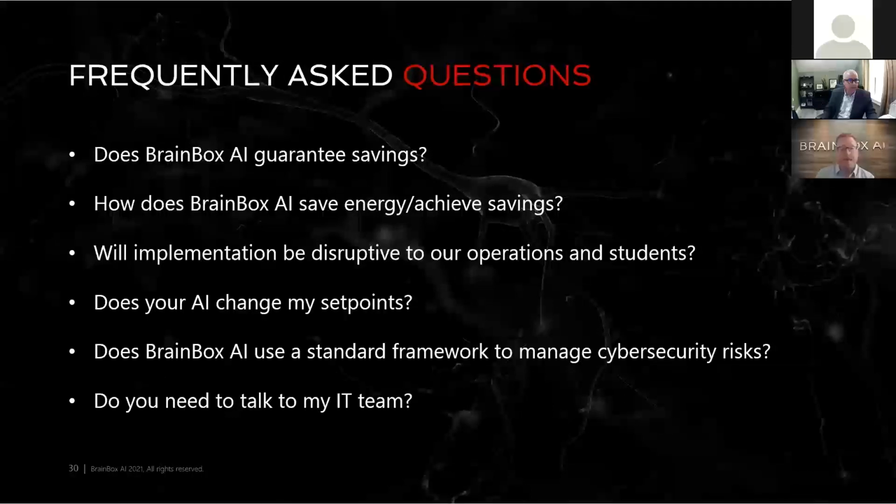So every 5 minutes it sends the data to the cloud and it asks, do you have a recommendation for me to implement down into the control system? If yes, it takes that and drops it, and then it closes that port. So I think the key for the cybersecurity aspect of the edge device is it's encrypted, it's VPN encrypted, TLS data in motion and at rest, and it initiates the connection from the device and not from the cloud.